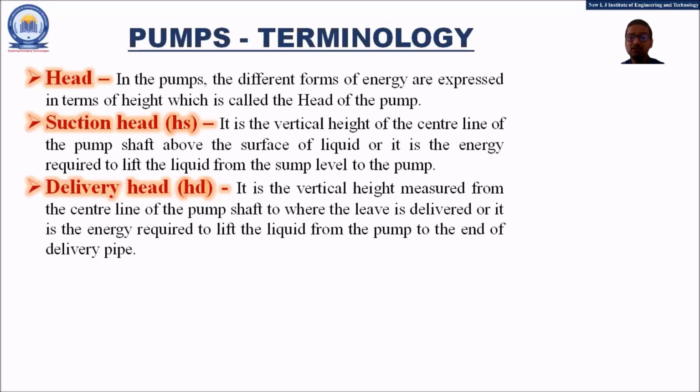Or if I consider it in terms of energy, then the delivery head is the energy required to lift the liquid from the pump to the end of the delivery pipe. That means for transferring the liquid from the pump to the delivery side, the delivery tank, the pump will require some energy, and this energy is considered as the delivery head HD.